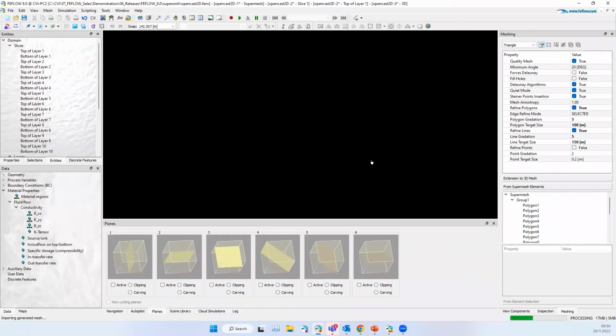And only if you use the option interpolate in the settings of TetGen will FEFLOW pass the data to the output tetrahedral mesh. The default option is also a non-quality mesh, so we call TetGen without a Q switch, which will obviously require later that you do a second mesh operation to improve the quality. It's almost done.